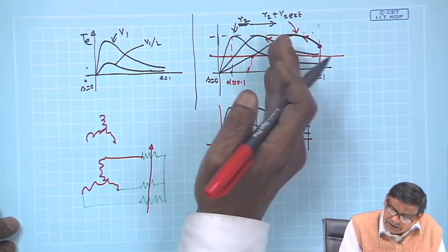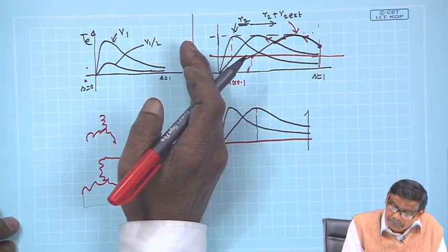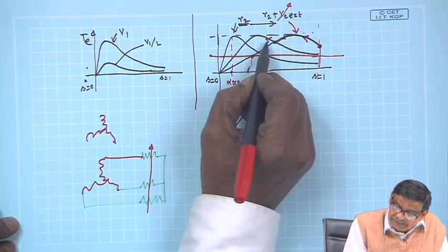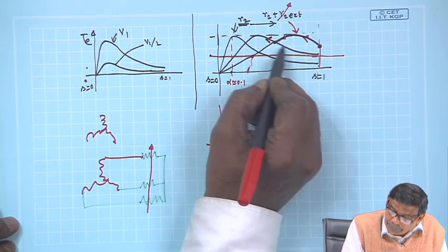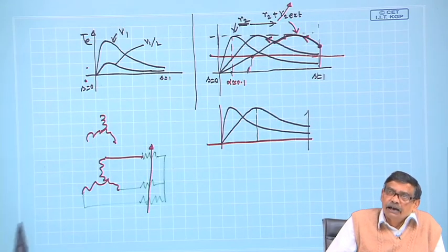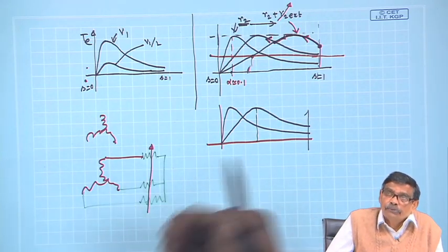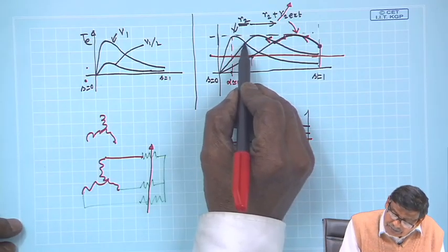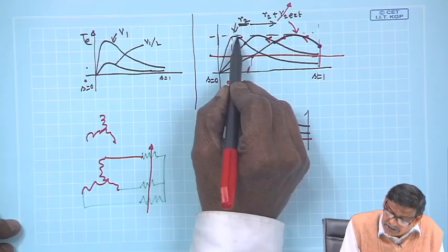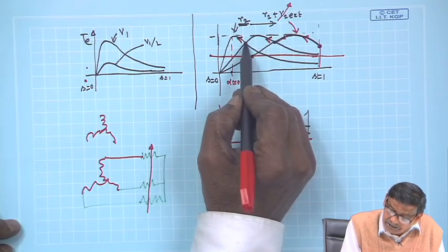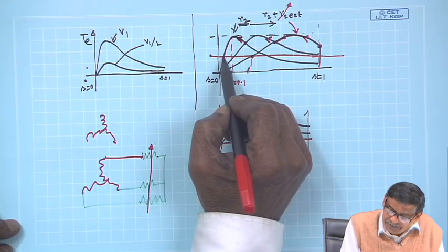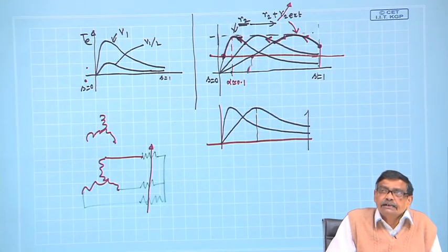Suppose I reduce the resistance a bit, that R2 external, which is variable, then it will follow some torque slip characteristics, which is decided by R2 plus R2 external now. Then once again, suppose you cut out the resistance further, R2 external make it 0, it will move like this and it will settle down finally here. I think you have got the point.